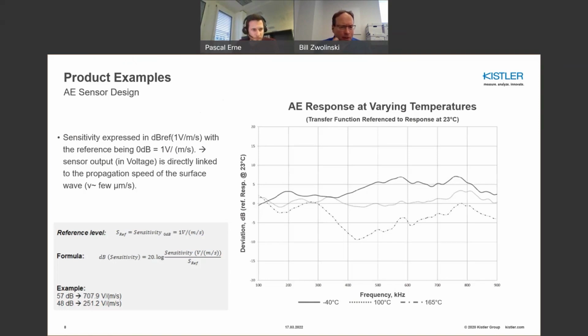When developing these sensors and when using these sensors, cabling is always the most important thing to a sensor in my view. I've seen poor cables being used in various applications, and although the sensor is great, you get poor results. So with cabling, you not only have to provide an ability to withstand the operational environment, with temperature up to 165 C, but obviously cables at higher frequencies are going to have some loss associated with them.